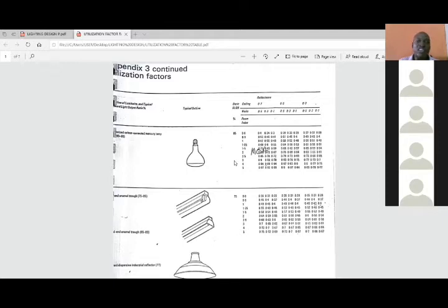We are also told the color of the ceiling was white, while the wall color was light blue. So these factors in combination with the particular fitting that we are actually deploying for the design will assist us in deriving what our utilization factor will look like.